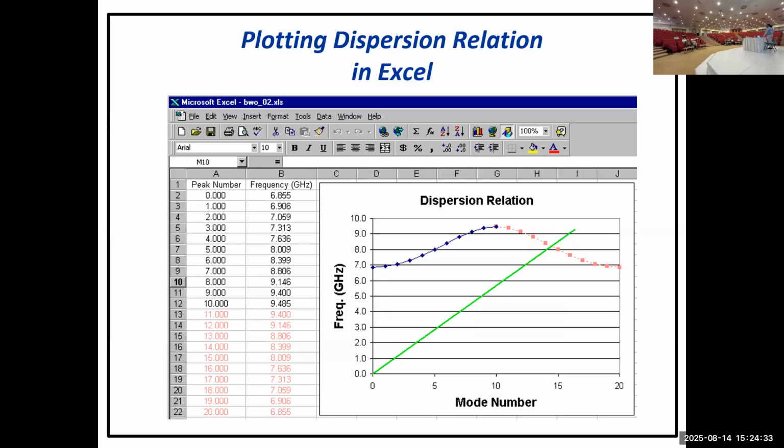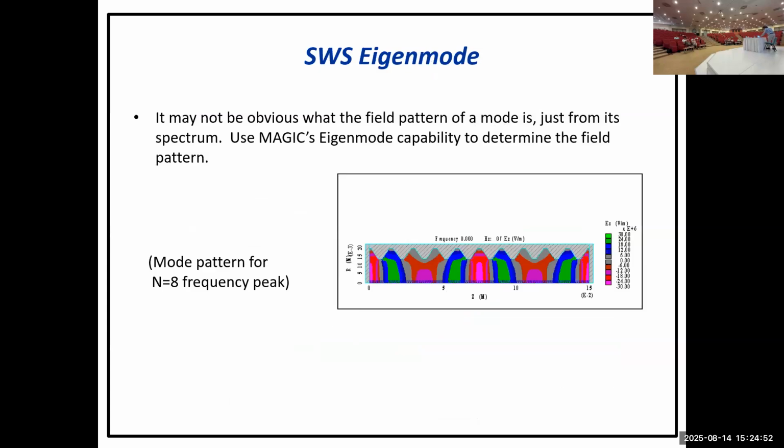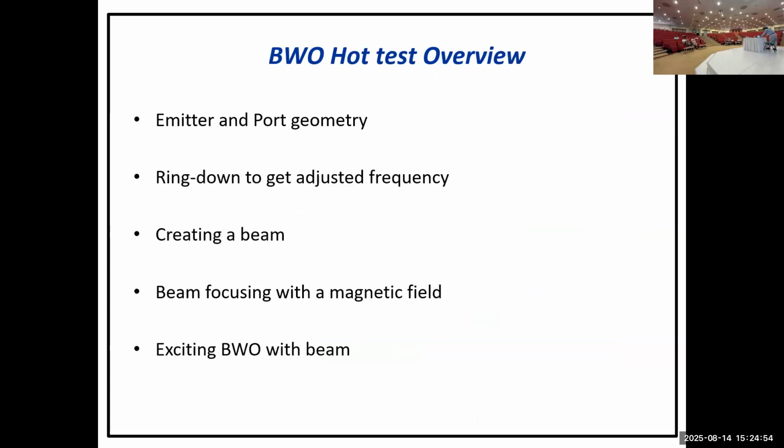There is another way, which is kind of the ideal way. In CST, we use periodic boundary conditions. We assume the structure is infinitely periodic to both sides, and then get the smooth curve. That gives you an ideal curve. It's not the actual dispersion curve, but good enough at least. This is in simulation, and then the next step is the eigenmode. In experiment, let me.